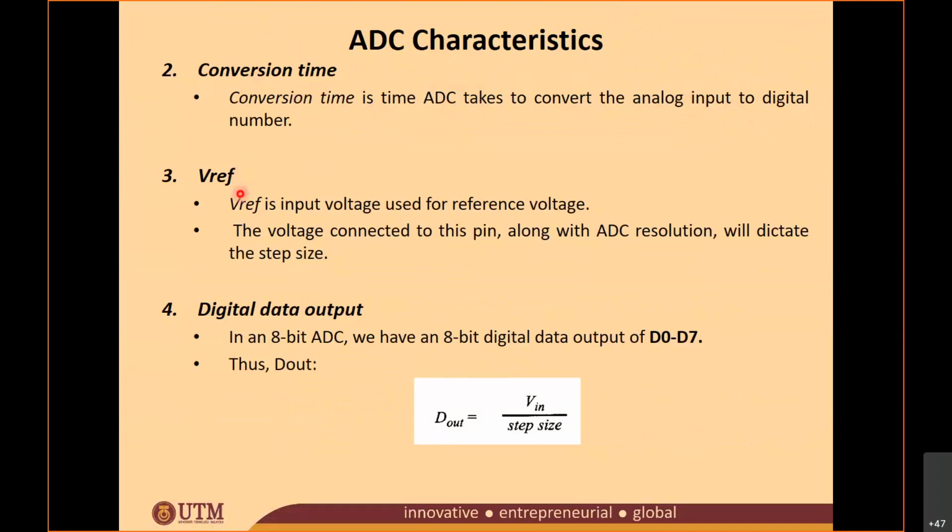And then we have VREF. Okay, so VREF is your V reference. It's the input voltage used for the reference voltage. The voltage connected to this pin along with the ADC resolution will dictate your step size. As we saw earlier, step size is equal to VREF divided by your number of steps, your resolution.